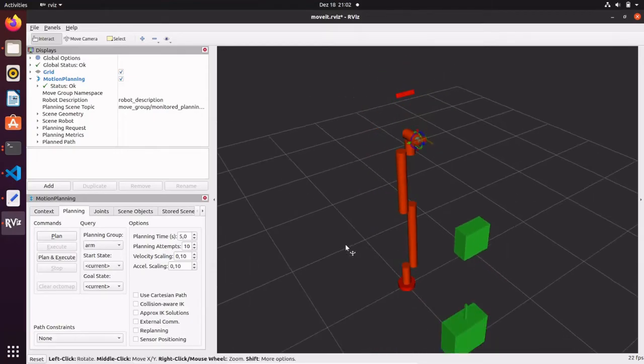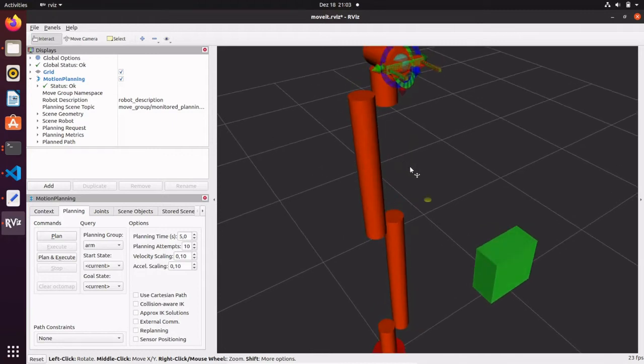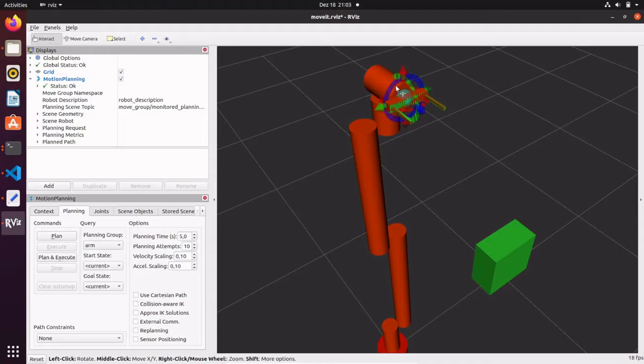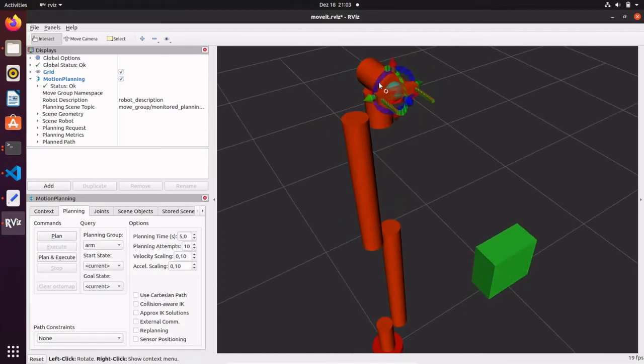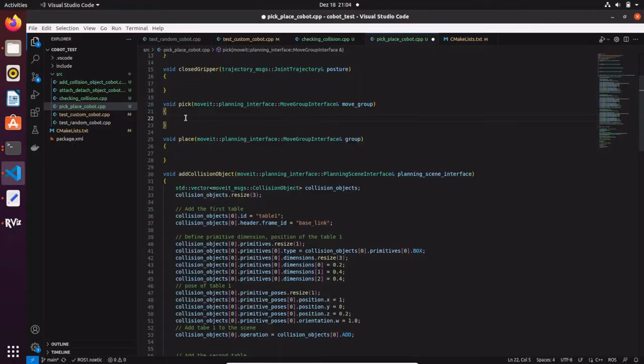Offline you can think about it, and you can have this in mind, how to pick an object. I understand if you struggle to visualize the movement that the TCP needs to have, but after some practice, you are going to understand better what is the angle that you will need to put as a new orientation setup of the TCP for the pick position. So we're going to discuss it later, but now after this introduction, let's populate the pick function.